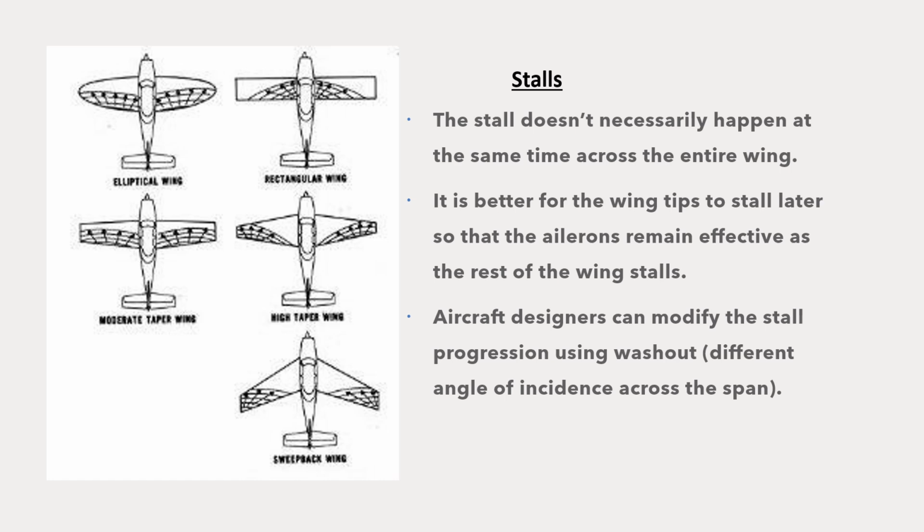When they design higher performance gliders, different criteria are more important than that. So the designer may not have done as much to make sure the stall behavior is nice and benign. So as you move past training and you start moving into higher and higher performance gliders, you are likely to encounter some that are a little bit less benign when they stall.